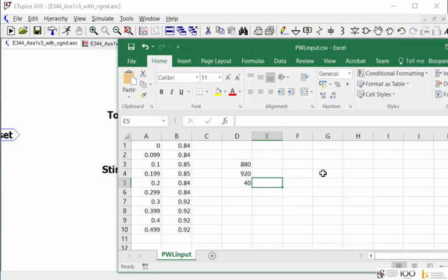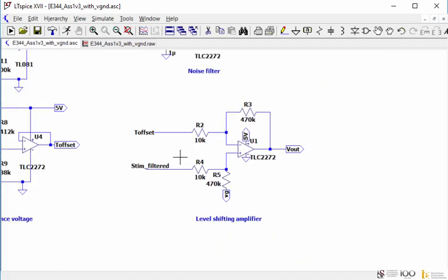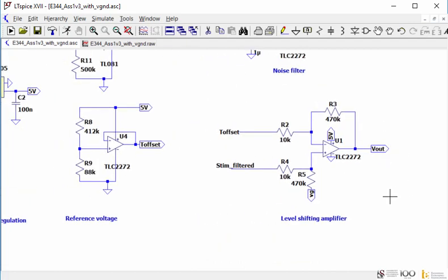I want that to go up 1.5 volts. So to do that, I need a gain of 37, more or less. This is obviously millivolts, so you need to multiply that by 1,000, so 38. So in this case, I chose 47 to blow it up nice and big so that I get a big output that captures as much of the range that I possibly can.